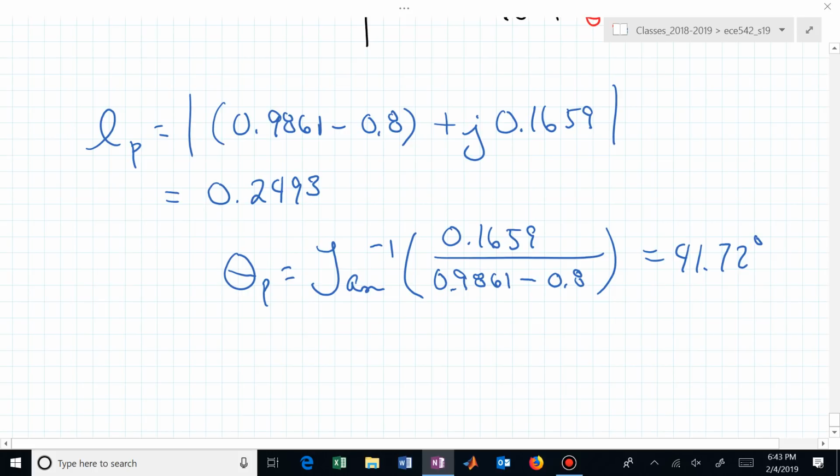So the very first step in converting or finding this discrete equivalent, I introduced some error. There's going to be some error between the continuous time solution versus the discrete time, but that error is probably very minimal in terms of what you would see in reality if you actually implemented this difference equation form of a low-pass filter versus implementing it with hardware. Your hardware might have more error because you don't find an R and a C value exactly like you wanted.